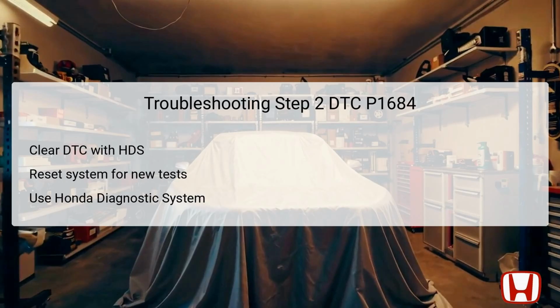The second step involves clearing the stored DTC using the Honda Diagnostics System, HDS, a specialized tool used for Honda vehicles. This step resets the vehicle's diagnostic system, preparing it for new fault tests. Clearing the DTC allows technicians to determine if the problem is persistent or intermittent.